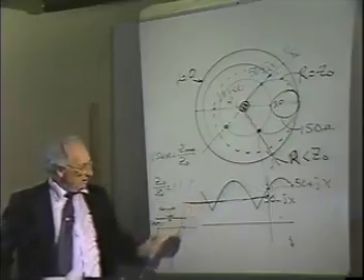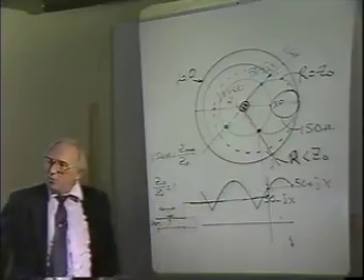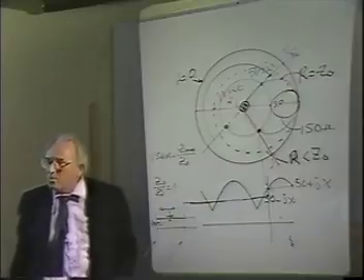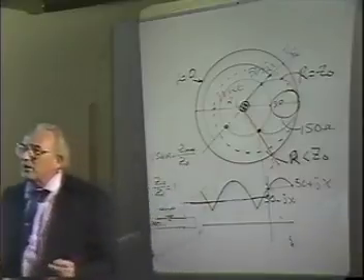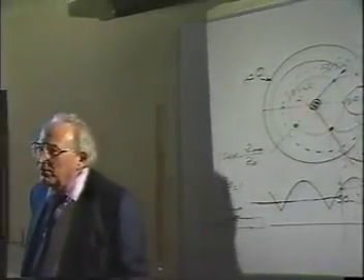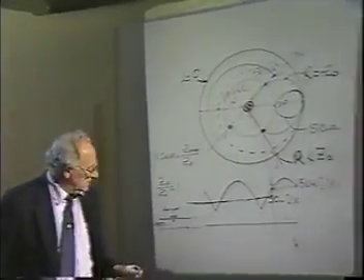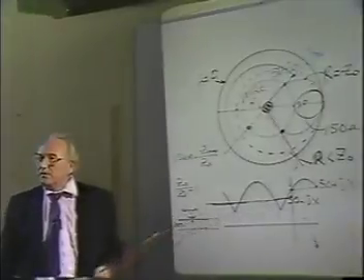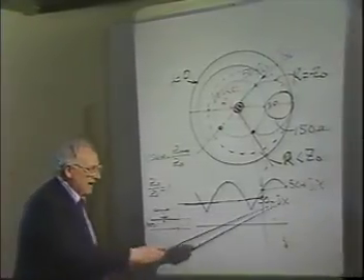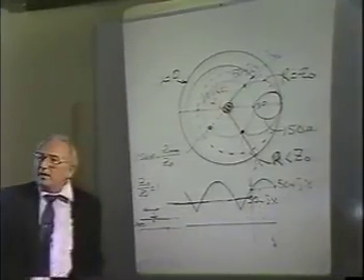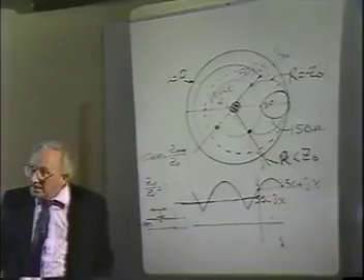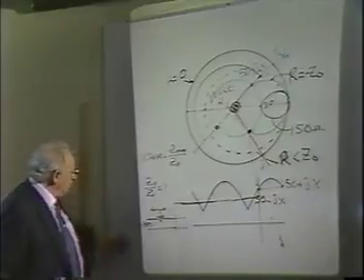But to do that, you find that it takes a 1.1 mismatch to cancel a 1.1. It takes a 2.0 to cancel a 2.0. You already know that. 3 to 1 to cancel a 3 to 1. If I cancel out plus JX, what do I cancel it out with? Minus JX. So there's two ways of looking at this.